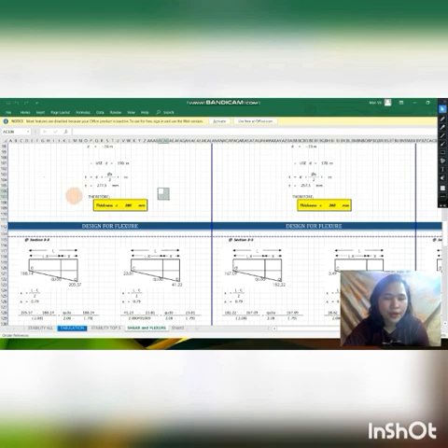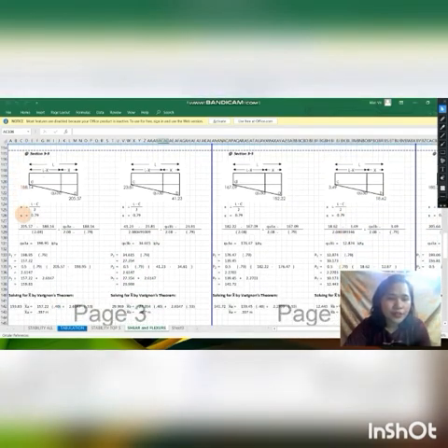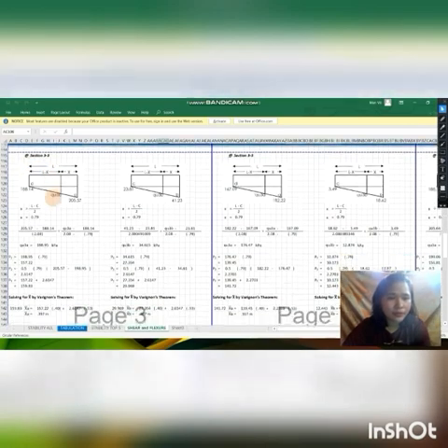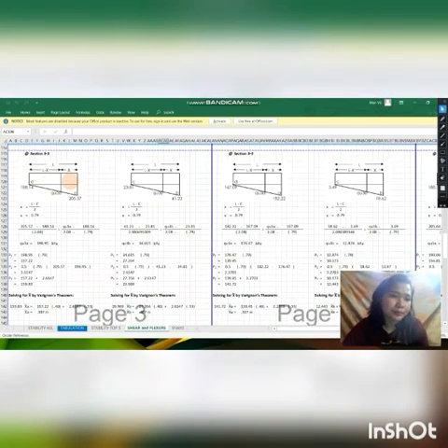Next, we will design for our flexure. For our flexure, the same as the one-way shear process, we will be using the larger value or average of the soil pressure. So for the flexure parallel to B, we have this figure, and like the one-way shear, we don't have minus D here because our design for flexure is like this one.